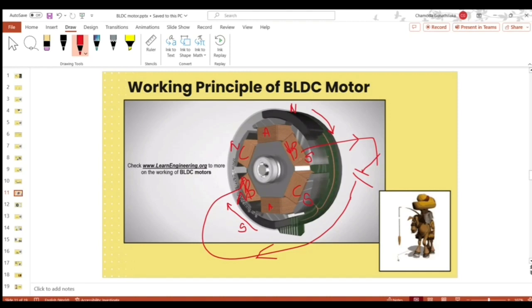Energize this B coil, it behaves as an electromagnet south pole. If we energize this coil, this C shows like a south pole. This permanent magnet is attracted to this C south pole. And again, this can be south pole. Again, south pole attracts, south pole attracts. This north pole is attracted too, but it never reaches because this south pole is hopping to each coil. South pole, south pole, south pole.